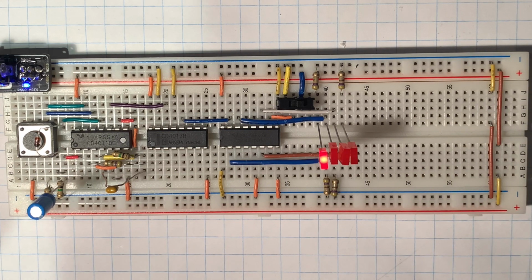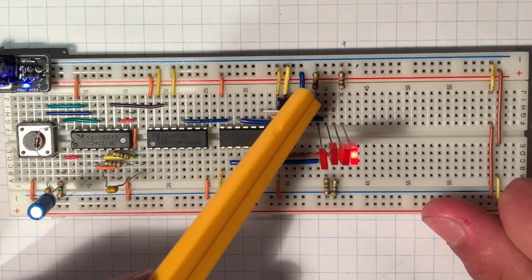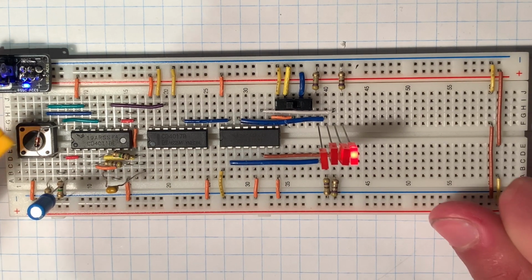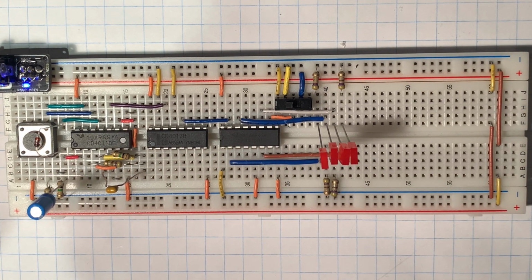When the reset pin is plugged in, it allows the counting to reset. Once it hits 9, it can go back down to 0 and repeat. The up-down feature of this pin allows the binary count to either go up or down. If the input is high, the circuit will count up. If the input is low, the circuit will count down.